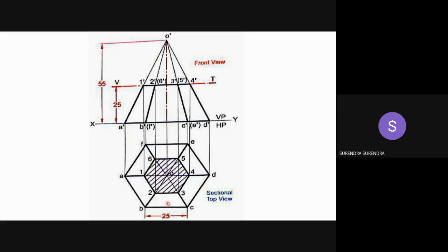And as this is the viewing direction, when you are viewing the hexagon in this direction, E and F points are hiding. So EO, FO are hidden lines. But EO, FO edges are overlapped with BO and CO, so there is no need to represent them as dashed lines.